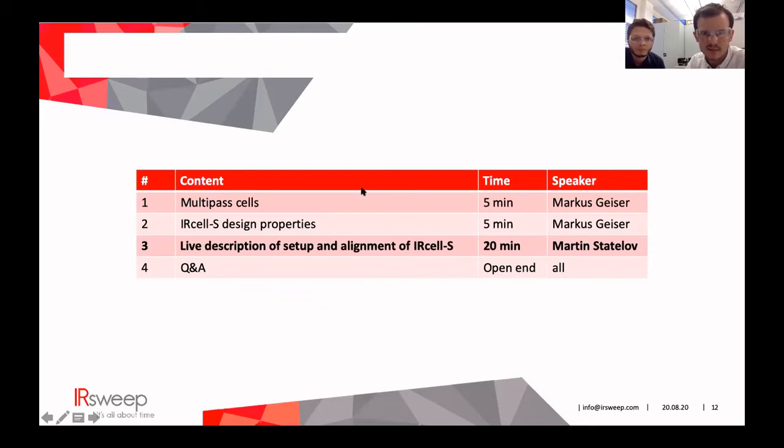What are the specifications of the QCL beam? Very good question. So it has a diameter of about 4 or 5 millimeters, and that is just dictated by the divergence angle of the QCL and how close we can go with the lens. The divergence I actually don't even know, because this is a manual collimation that we have here. So it's not a fixed factory-made package, but it's home-built for our purposes here.